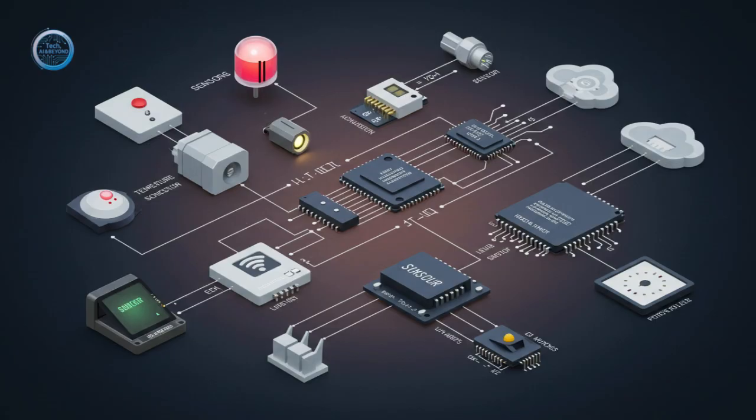Exactly. Now, as for common types, temperature sensors are everywhere. Think smart home thermostats, controlling your HVAC, monitoring industrial processes, or even ensuring the integrity of the cold chain for food and pharmaceuticals. You often see components like thermocouples, RTDs, or simple integrated circuit sensors like the DHT11 or DHT22, which handily combine temperature and humidity sensing. Right. I've seen those DHT sensors in hobby projects.